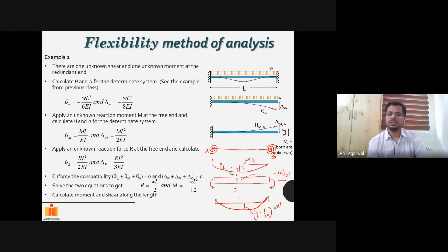members which are allowed to yield. So for example, for extreme load conditions, often the members yield at the ends. Okay, so if they yield, what we do is that whatever is the yield moment capacity of the member, that much of moment is applied in the negative side. So on the positive side, only the balance is the demand.